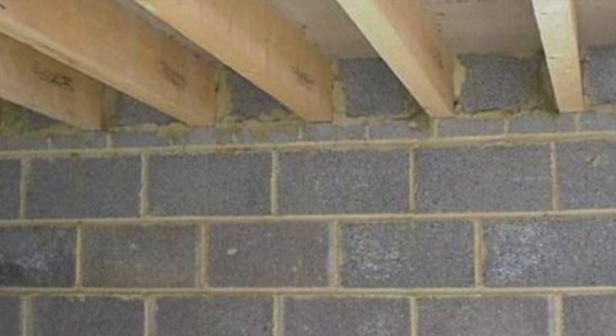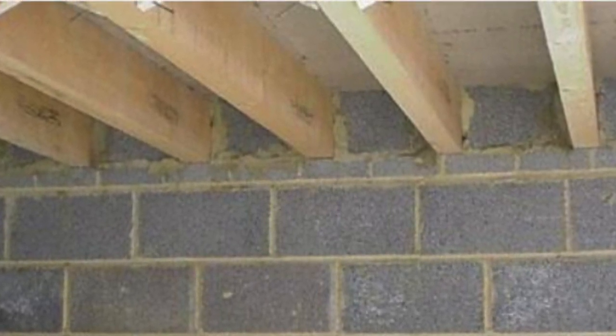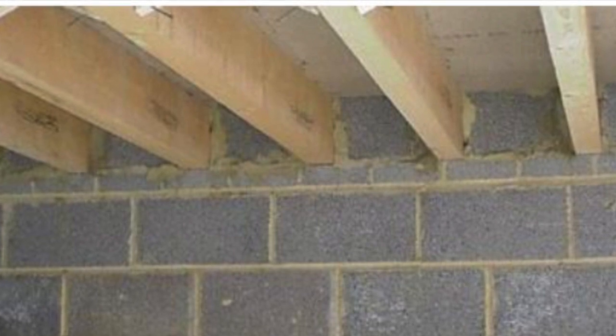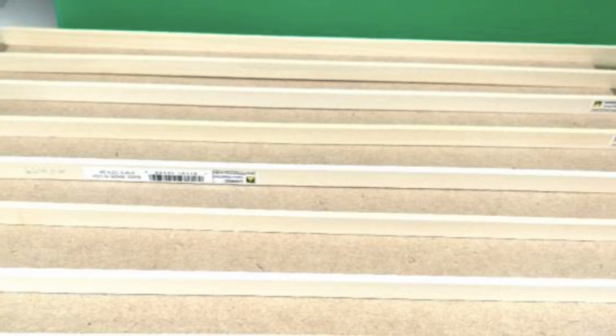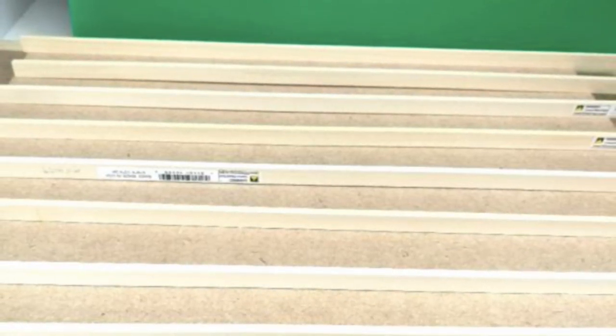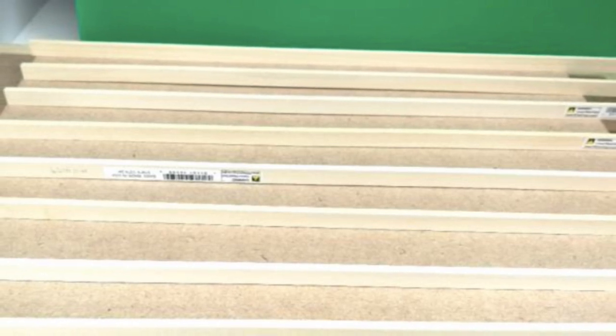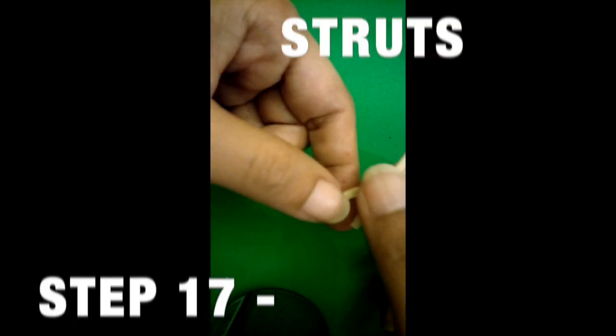The size of the floor joist is determined by spans between supports, total load, spacing, and quality of timber used. On the working model, we are using 8 units of basswood strip. One end of the floor joist is attached to the wall plate of the internal wall, and the other end is hung and nailed to the beam.